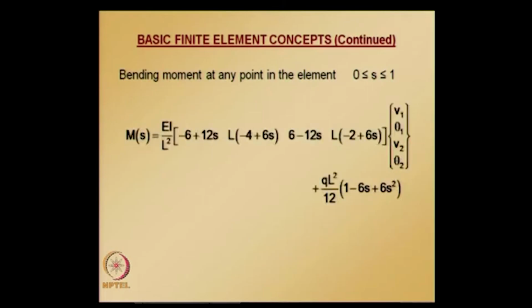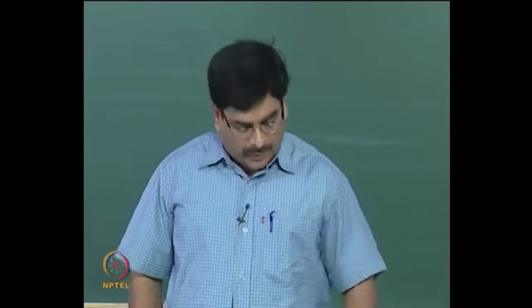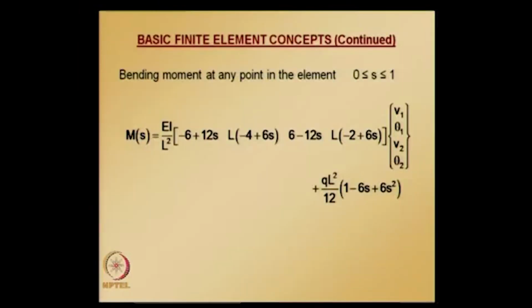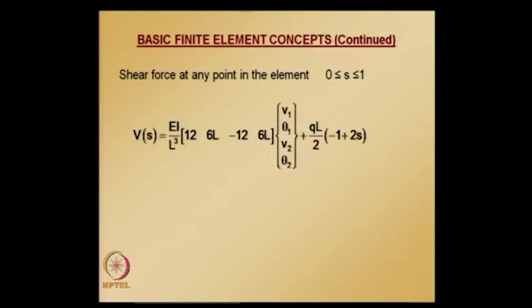And next, the bending moment at any point in the element is, as usual, interpolated using the nodal values, and over that you superpose the fixed end moment solution. Similarly, the shear force at any point in the element is given by this one.